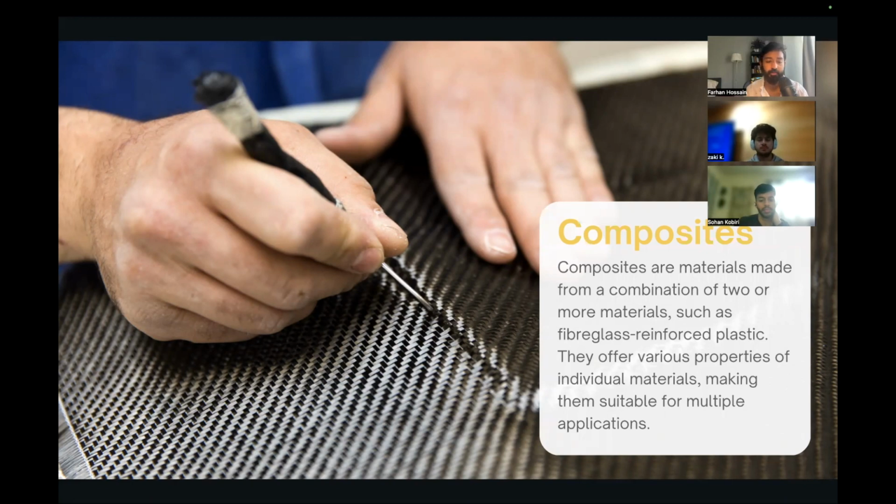And you'll see that there's a weave pattern. That weave pattern is used for aesthetics. That's true, but its primary purpose is actually to dictate which direction the tensile fibers are, to help you determine which way you're going to design your product to have stiffness or strength in that direction. So keep that in mind.